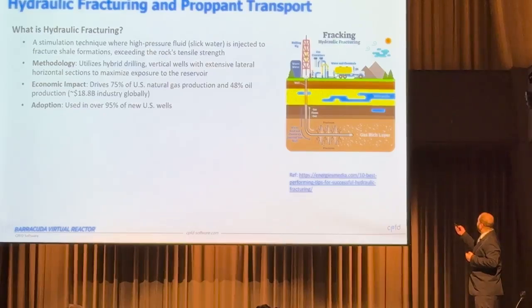That is what is known as hydraulic fracturing. So the way to do it is you pump from the surface. You bring in a truck which contains a slurry, essentially with some sort of slick water. So it's essentially some sort of a non-Newtonian fluid. You mix some polymer in the fluid to make it more non-Newtonian and viscous.